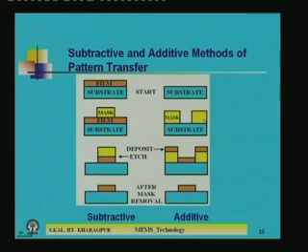What is the mask? Means photoresist. You can see the difference here. First film, that film may be either aluminum in case of metal or maybe silicon dioxide. So, we have coated first, but here what we did, first it is coated with photoresist and then on photoresist we pattern it, and after that we deposit the desired metal or silicon dioxide.